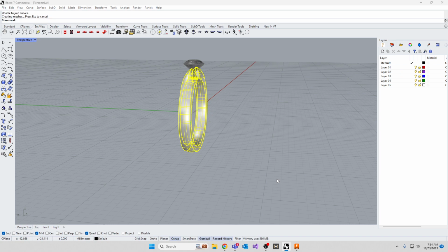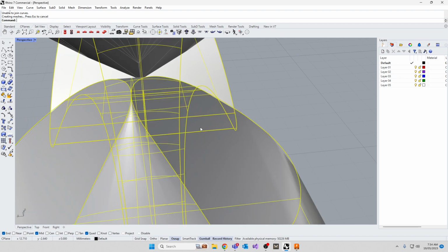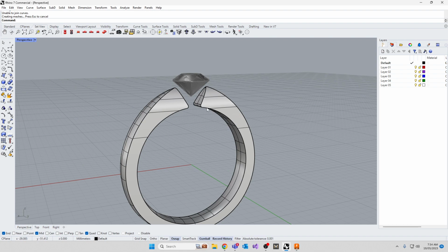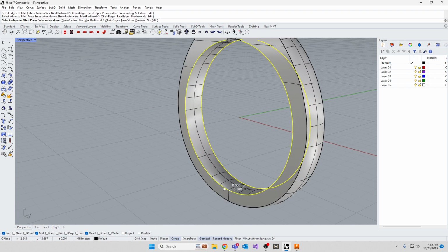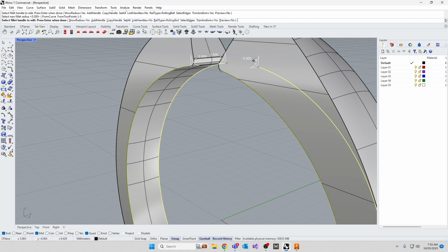I have a suspicion that that funny little point up at the top is going to bite our bums in a minute. Pretty much okay, I think. Alright, so if you wanted to, you can now go a little bit further. You can play with it, give it a bit of a fillet, like a variable fillet to break the corner even more. I suspect this is where you're going to see this thing break. Alright. Fillet edge. I want to go 0.5, but I want a variable one, so I'm going to click here. I'm going to click here. And press enter. Up at the top here, I want 0. I don't want any fillet there. I only want the fillet to come down at the bottom.